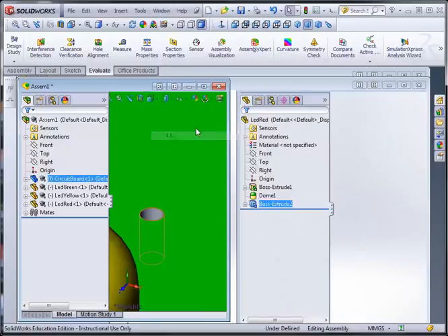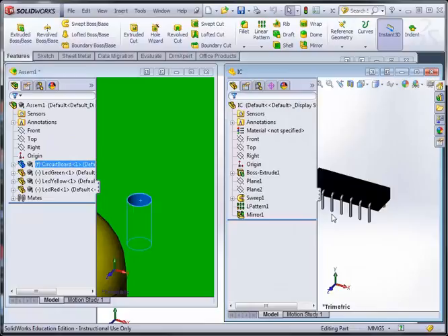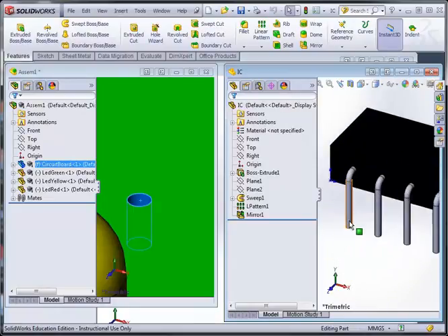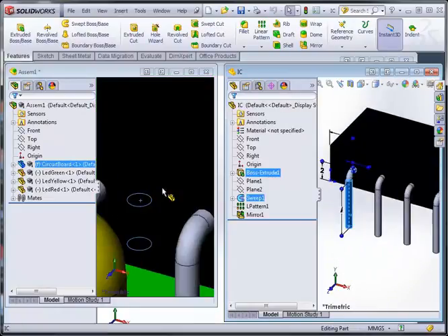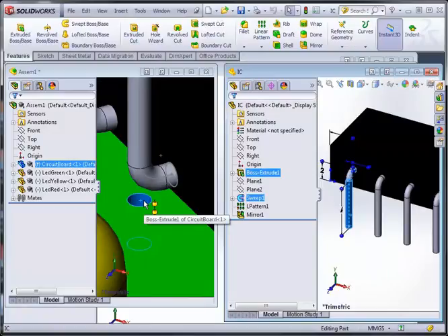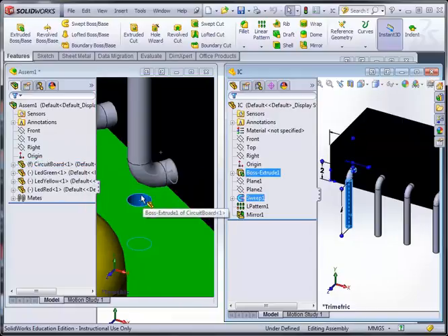open our IC, stack it to the right side, click the correct edge, the correct face. Now, if you see, it's being made upside down. Now, we're not looking for that, but that doesn't mean you have to cancel the mate and redo it, because every time you place it, it will still give you the same orientation. So once you see that symbol, drop it down.